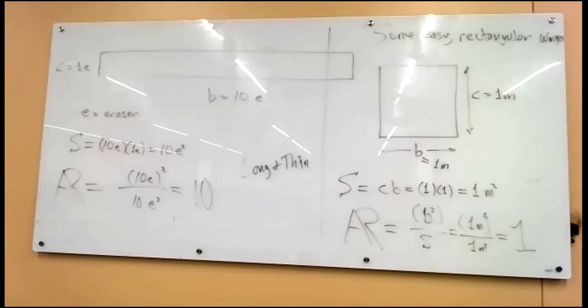So in that, you'll need to build a finite wing, and there will be calculations in the scoring of that based on the weight, because if you build your wing too long and thin, then the weight goes up because you have to have the structure to support that. So we'll give you some more tools about how to do that and how to design your wing for that.